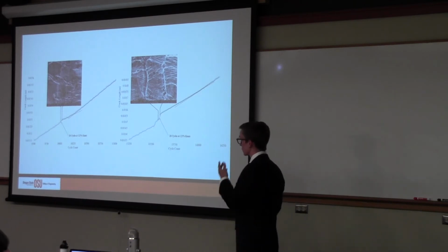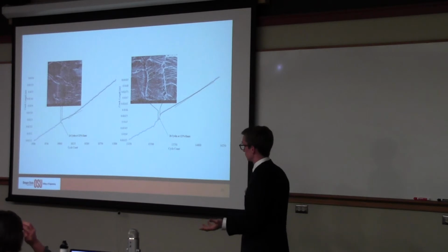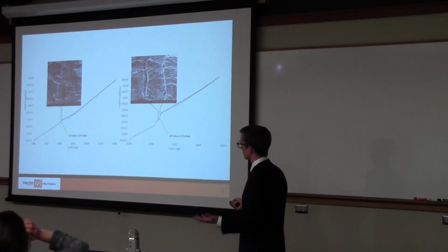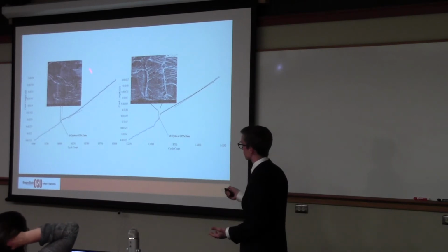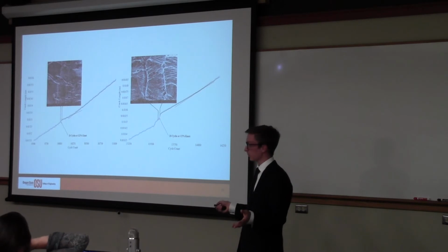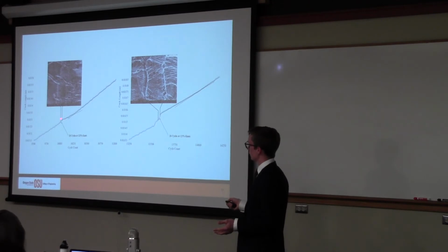Was it slowed down? Is it decelerating after the overload period, like you would see based on classical theory about overloads? And the interesting thing that we find is that this overload was applied below this threshold that we keep talking about, this threshold of time dependence. And on the fracture surface, you see those markings. You can tell where the overload happened. And you can tell that the overload had some effect when you do this kind of linear intercept method. You can see that there's a slower crack growth rate for the first few cycles.